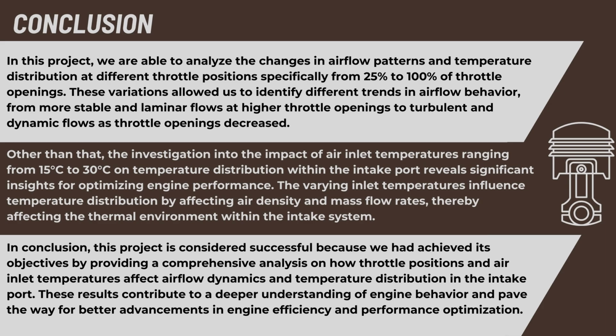Other than that, the investigation into the impact of air inlet temperatures ranging from 15 degrees Celsius to 30 degrees Celsius on temperature distribution within the intake port reveals significant insights for optimizing engine performance. The varying inlet temperatures influence temperature distribution by affecting air density and mass flow rates, thereby affecting the thermal environment within the intake system.